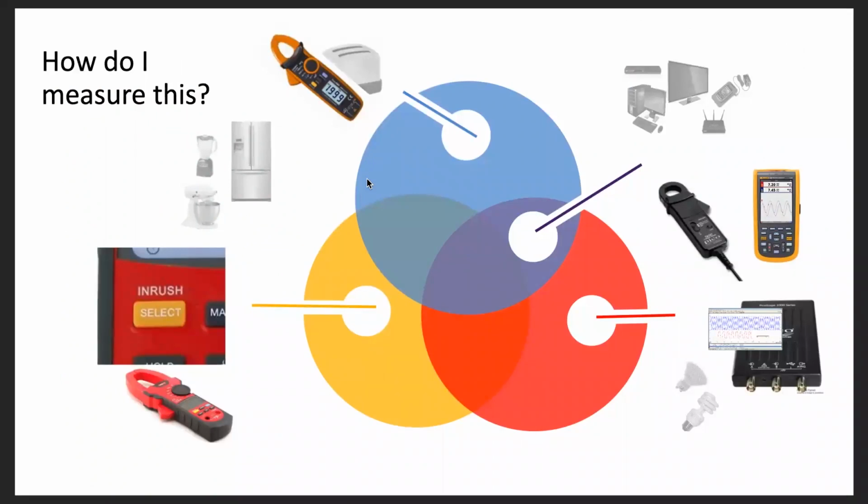So again, to measure those types of loads or those voltage characteristics, it's easy enough to measure the continuous current for loads with a standard ammeter. For motor loads or any type of inrush detection, you'd need to have that inrush feature built in on an ammeter, and those are pretty common nowadays and not too much more expensive than a standard ammeter. As far as measuring transient spikes, it's really not necessary, but this graphic just shows the type of equipment that would be able to measure that.